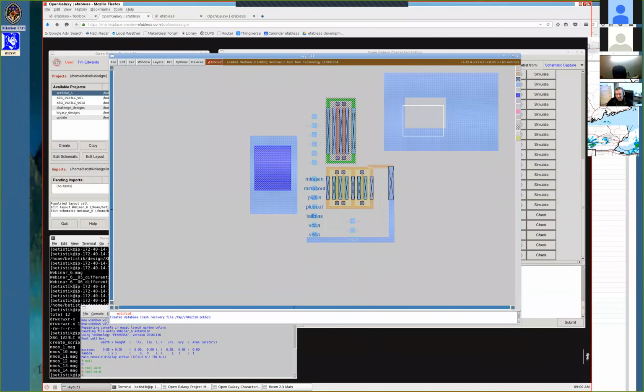So that's not metal. That's a hole, but there are special DRC rules having to do with holes that make them different from metal layers. I generally don't use them. To me, it's pretty much equivalent if you just leave it as an open space.